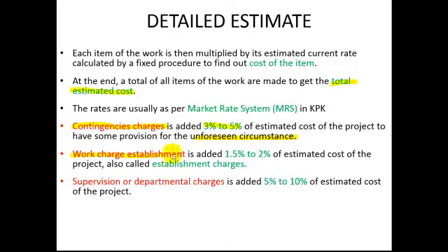Then we add the work charge establishment, which are basically the charges for the establishment of the project, and these charges are added as 1.5 to 2% of the total estimated cost of the project. We add the supervision or consultant charges, or the departmental charges if the project will be monitored by the department itself. So we add a percentage of 5 to 10% for the supervision charges of the project.